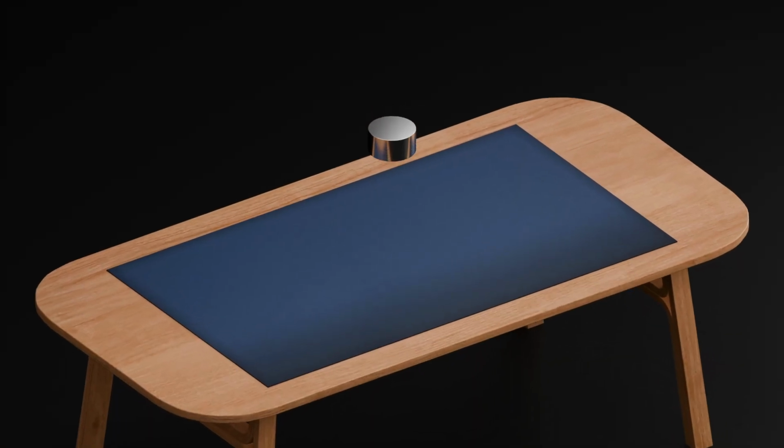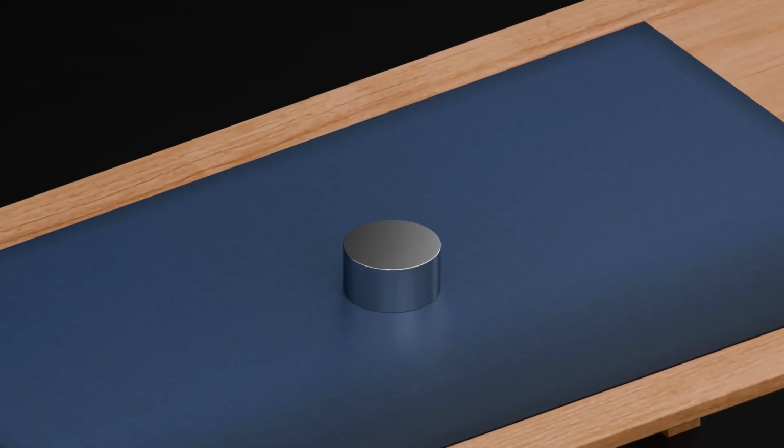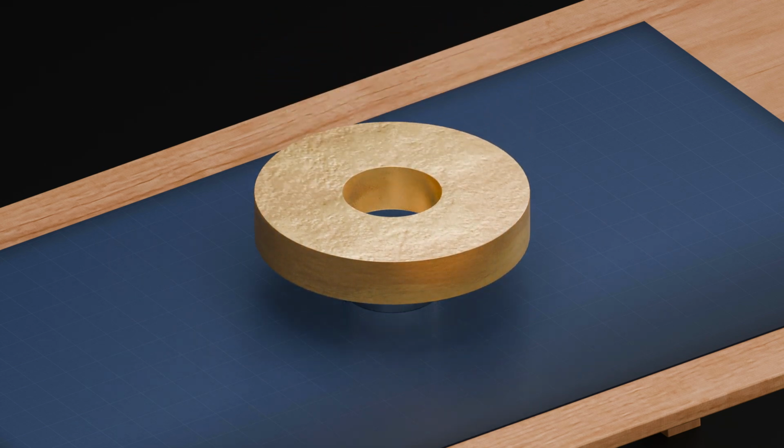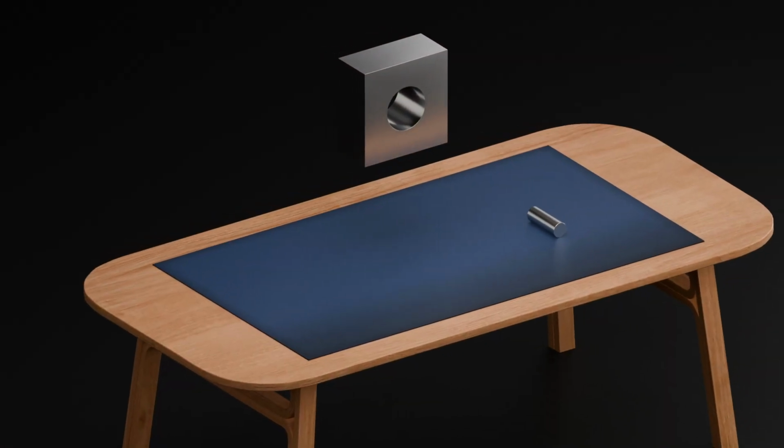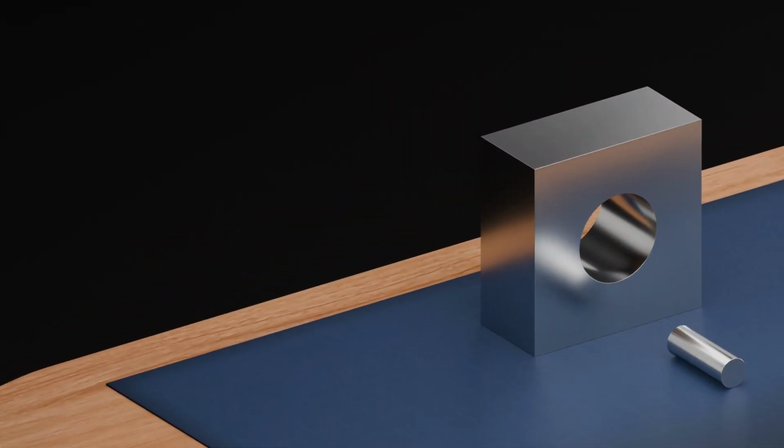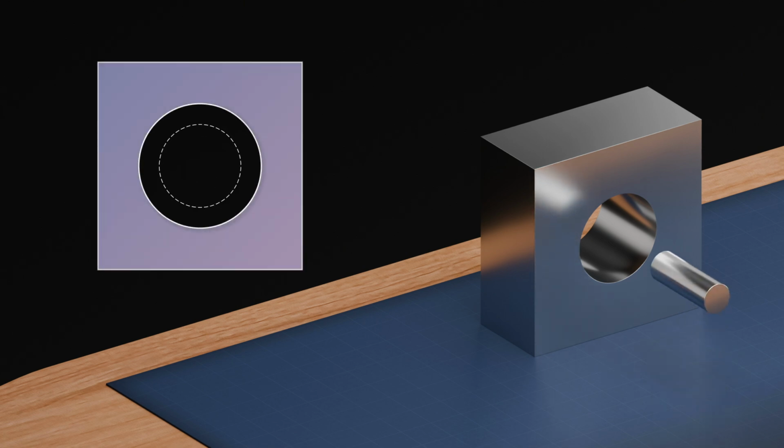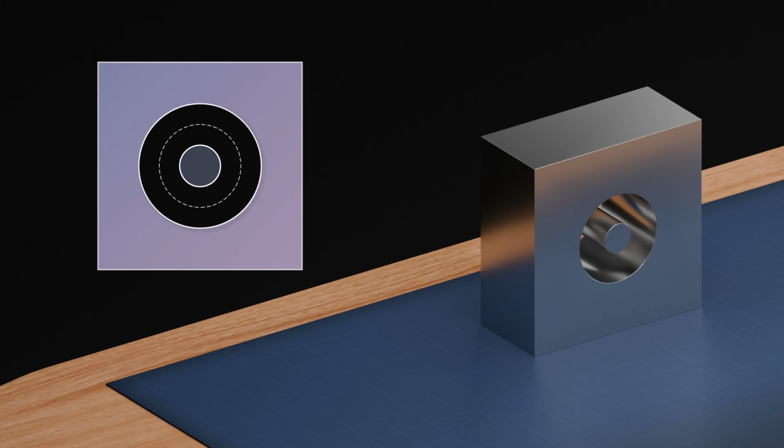The MMC concept is primarily applied to mating features, such as holes and pins, to ensure proper assembly between parts. In most practical situations, our main concern is whether the parts will assemble successfully, especially when both parts are at their worst case size conditions. That is where the MMC concept becomes extremely useful.